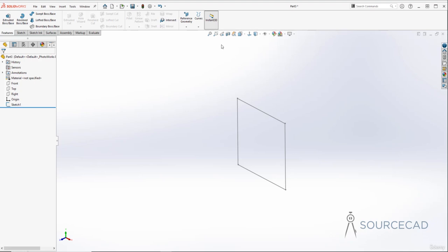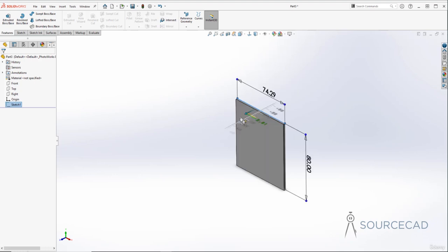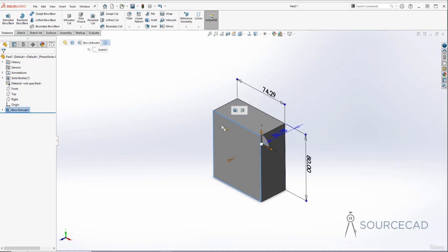So now with this thing selected, I'll select the sketch, and when you move your cursor, select it, slightly move it, and you're gonna see this. Now if for whatever reason this arrow doesn't show up, then click on this sketch again and the arrow will show up. Now using this arrow, you can add extrusions. Now once you have finished extruding this, you can add other features, like you can add a draft angle, or you can create a cut.